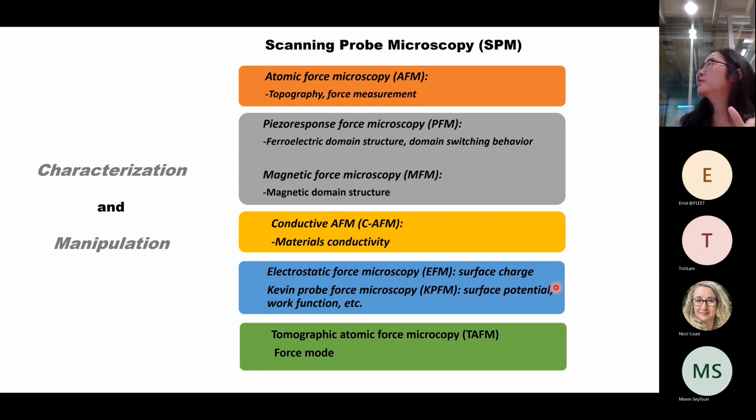It can also be used to study the surface charge, potential, and work functions of the materials. And recently we developed tomographic atomic force microscopy, which I will introduce a bit more later. Basically we use a very hard tip to remove the surface of the material, and then study the features of the material after removing the surface.